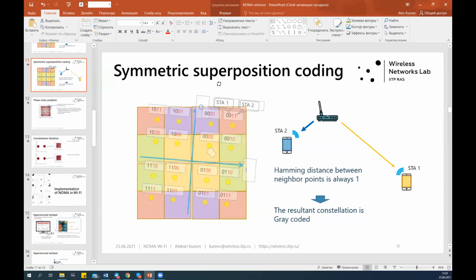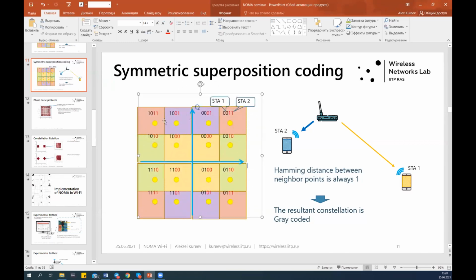We can at first transform the general constellation which corresponds to the primary frame, and then we transform the constellation which corresponds to the secondary frame. After this step-by-step equalization, we can obtain the same equalized constellation which corresponds to the NOMA frame, and then do the same parallel constellation demapping.